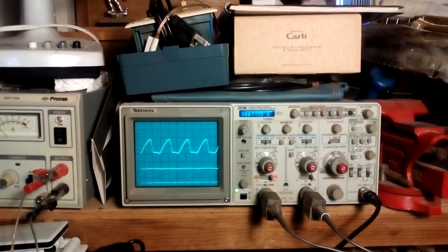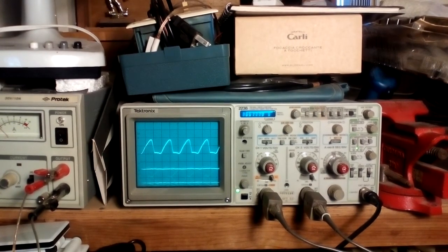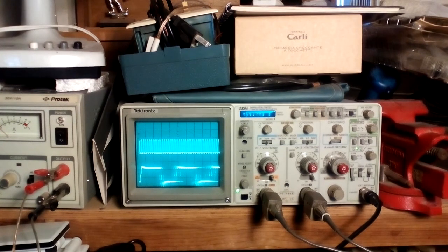And this is what it looks like. The TTL oscillator looks like it's about, well, the counter says 8.6 megahertz. The horizontal scale is 0.05 microseconds. So you can see that the output is only ones and zeros, and what's changing is the relative time that it stays ones or zeros. And so it's a 1-bit A to D converter.